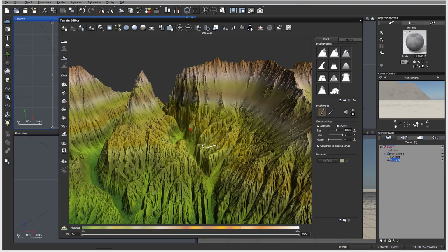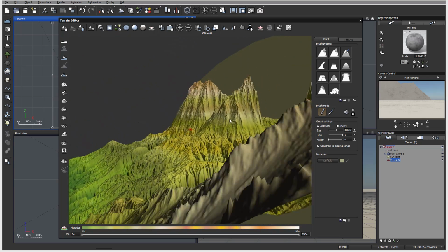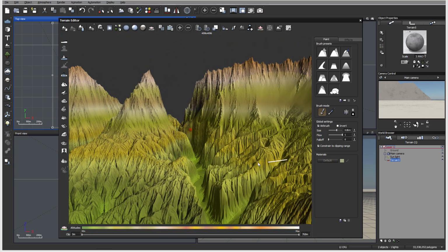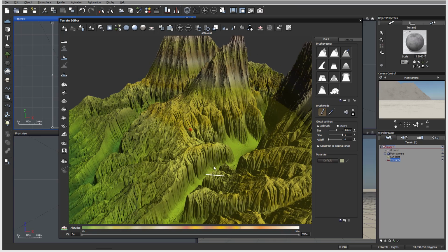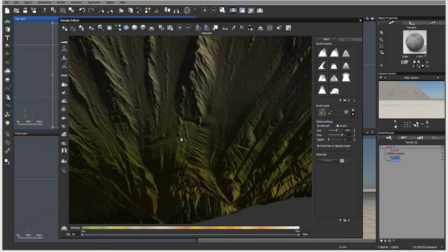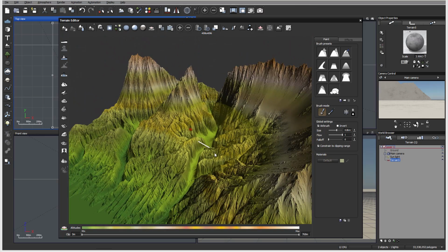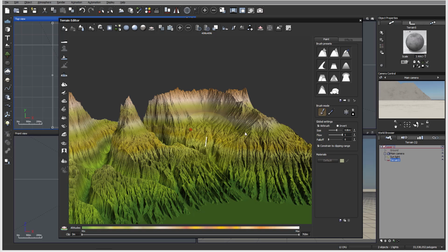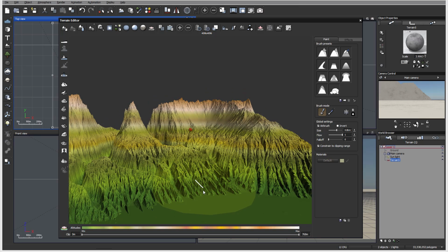So you can see it's quite high resolution, with a little bit of stretching right here, and this is a problem with any height map versus procedural, because we have only one view, we don't have a side view. So whatever the height is, these Z sides will be stretching, so we'll have stretch problems. You can fix this by applying an additional function that will help add details. Or we can also reduce the overall height of this, just shrink it down a little bit. But overall with a height field you will have a problem with stretching in these areas.